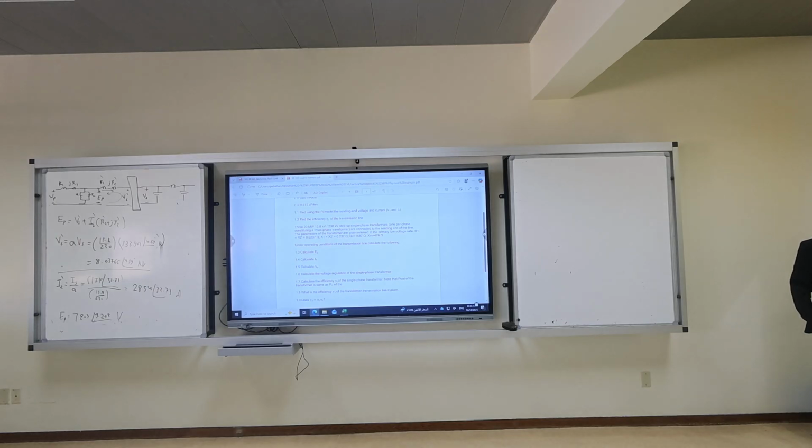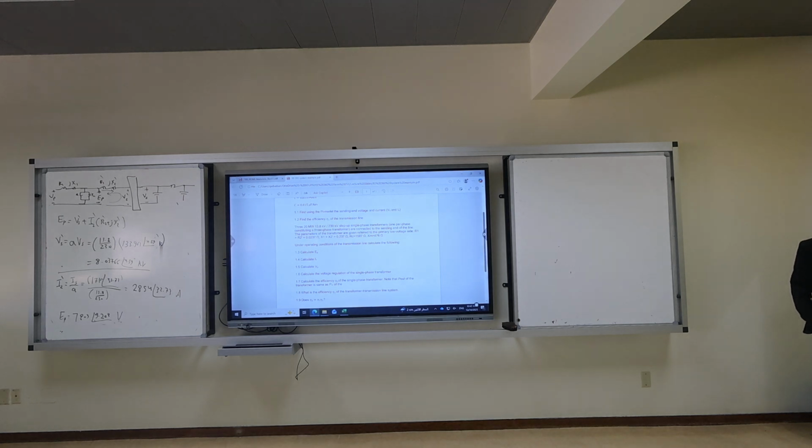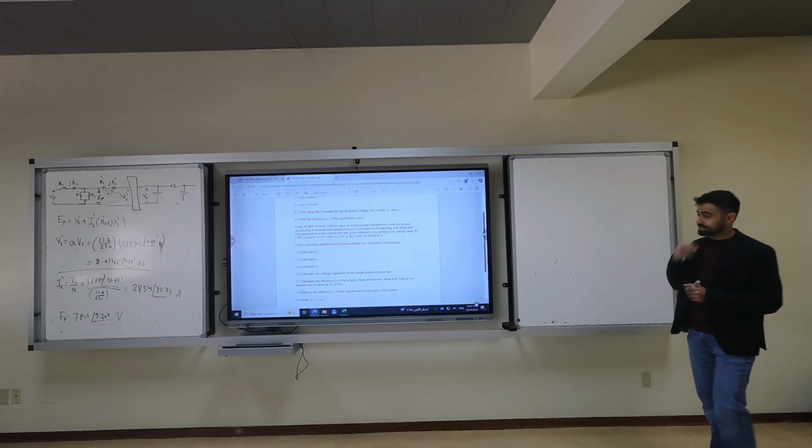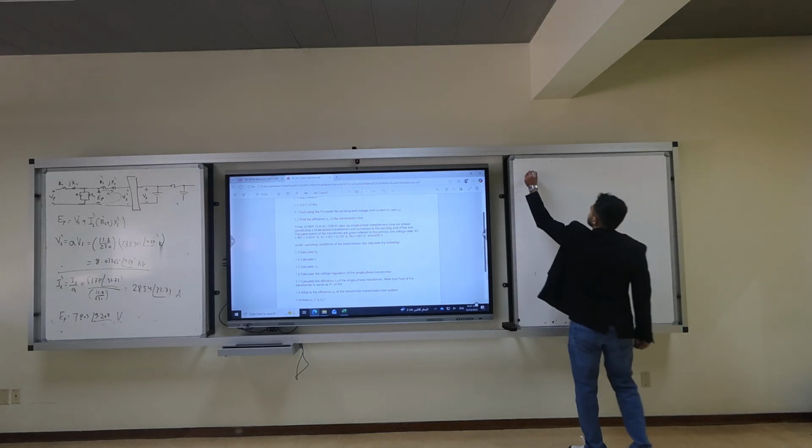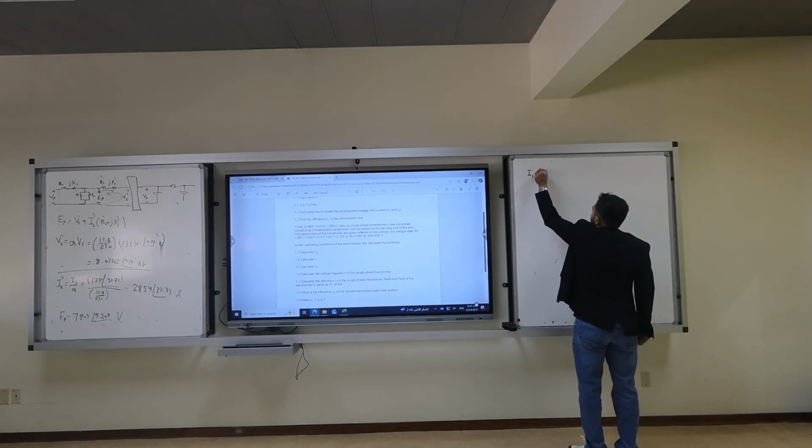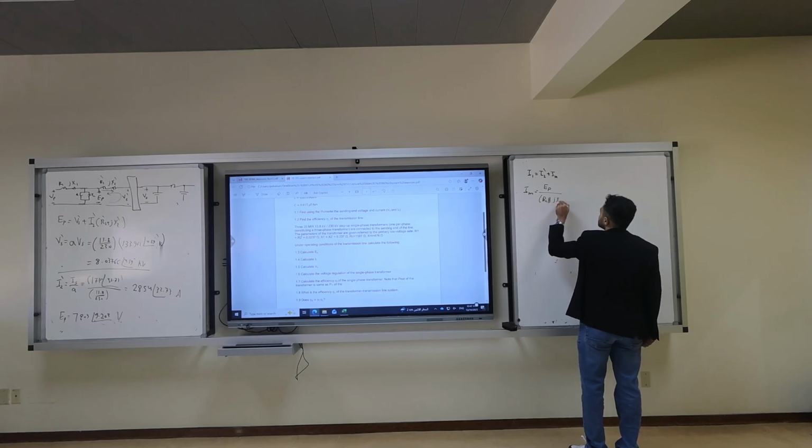So hopefully in the exam I will ask you up until EP, okay? Hopefully nothing after. But what is I1? I1 is I2 prime plus IM. What is IM? IM is EP over the parallel combination between RC and JXM.